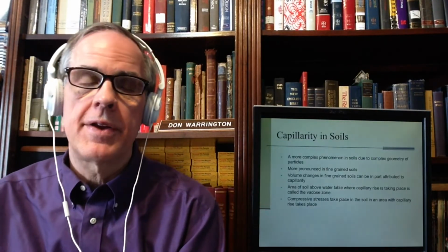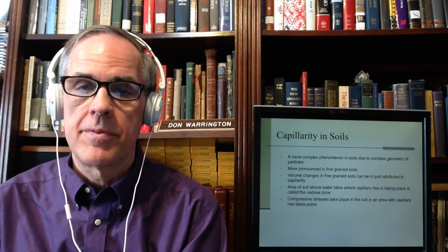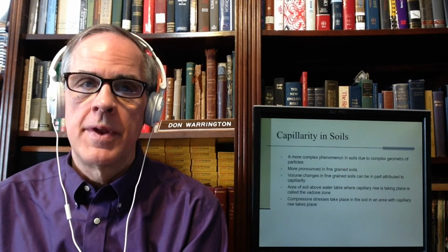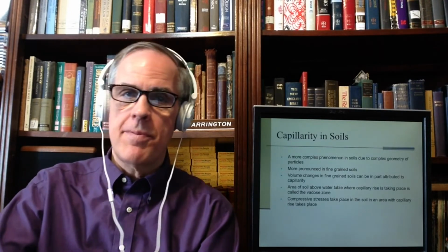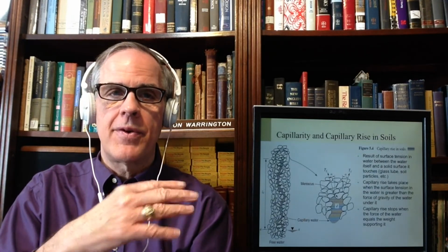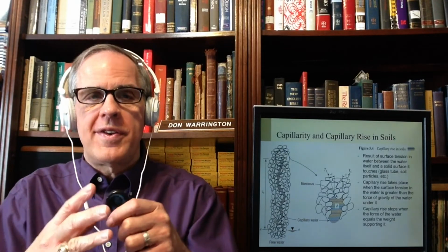Capillary rise is a more complex phenomenon in soils due to the complex geometry of the particles. It's more pronounced in fine-grained soils because most capillary rise assumes a straight tube, and we're going to use the straight tube approach. And obviously, as your particles get smaller, your voids get smaller.